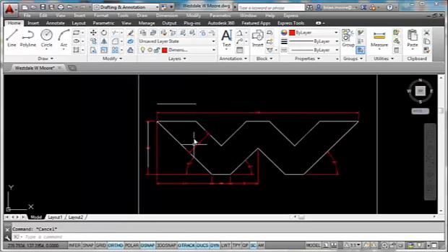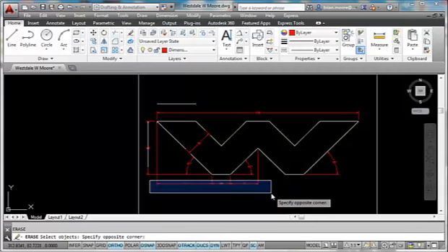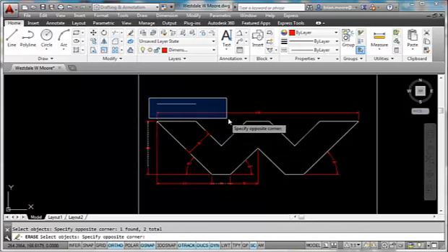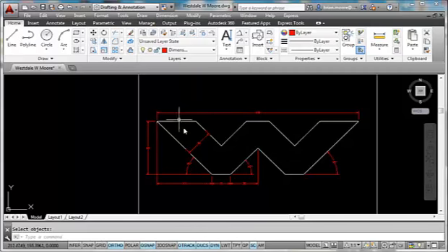So now the last thing I need to do as far as dimensioning is to get rid of these lines that are underneath. Otherwise, when it prints out, that's going to look poor. So I'm going to do the erase command, E for erase, and I'm going to use a window this time because that selects only things that are fully within. So if I do a window like this, none of the dimensions are fully within that window, so the only thing that's going to get selected is that line. I can do another window up here, and another window like that, and I get both of those lines. And then I can hit enter, and I've gotten rid of all the lines underneath.